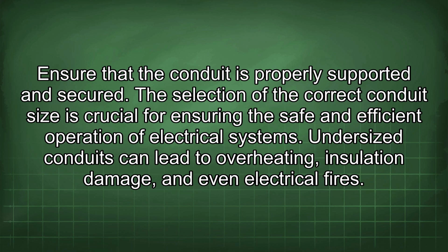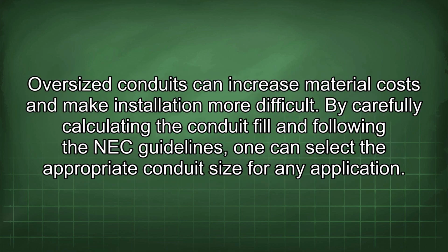The selection of the correct conduit size is crucial for ensuring the safe and efficient operation of electrical systems. Undersized conduits can lead to overheating, insulation damage, and even electrical fires. Oversized conduits can increase material costs and make installation more difficult. By carefully calculating the conduit fill and following the NEC guidelines, one can select the appropriate conduit size for any application.